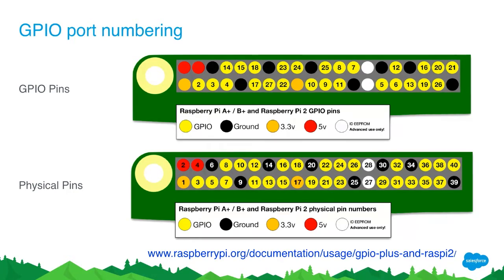Something else we should mention is you'll see the voltages on the pins. It doesn't sound like a very big difference between 5 volts and 3.3, but it is significant. Make sure that your sensors or your devices match the voltages on these pins, because if you put 5 volts onto a 3.3 volt pin, you're probably going to damage the Pi. And all of the yellow pins for data in and out, those are also 3.3 volts. And by the way, the pinouts and the numbering schemes, everything is identical between the Pi 2 and the Pi 3.